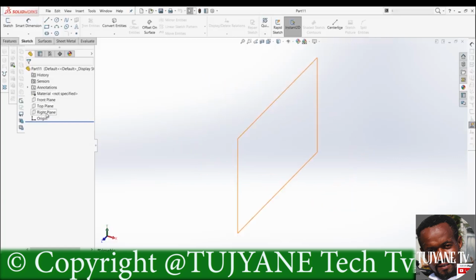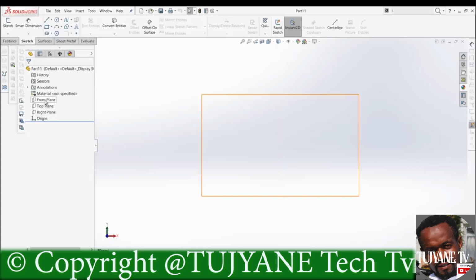In order to create a 3D part, you will first need to make a 2D sketch. And in order to create a 2D sketch, you will need a plane. First things first, select a plane by clicking on one of these 3. Now we go to the Sketch tab and activate the sketch mode here. Once you do that, you see these buttons: Rebuild and Close. Rebuild saves your sketch and exits the sketch mode, and Close, well, exits it without saving anything.